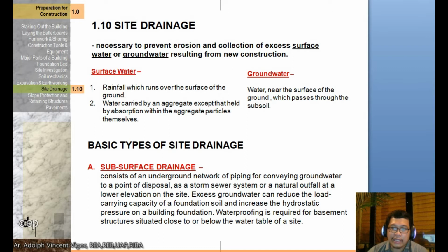So we had to work with a structural engineer to redesign the foundation of the project again. That's why it's really important, class, someday in your construction, to first make an investigation of the soil conditions of an area before proceeding with the building.